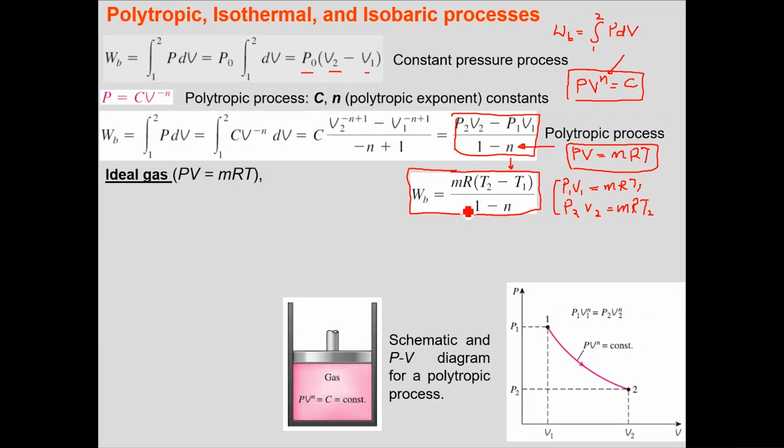Now, with these two expressions, let's say we have a fluid which is undergoing a polytropic process isothermally. The first assumption is that our fluid is an ideal gas, and the process is taking place isothermally. If these two assumptions are valid, we say that PV is equivalent to MRT. Now, instead of writing T, we write T naught to represent a constant. With M constant, R constant for the gas, and T naught constant, we can say that PV is essentially equal to C. This is valid for an ideal gas that is following expansion or contraction isothermally.